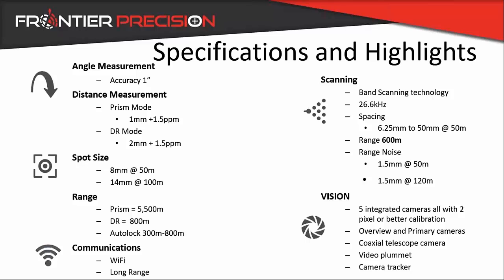So 26,000 points per second, that's going to be one of the most common questions. So it is operating like a true scanner, not like you saw with a VX or an S7 that stops, points, and shoots. And it also has scanning capabilities in the workflow so that even when it's doing a full dome scan, it's just going to blow by all that fluff noise if it shoots into the sky, as an example.